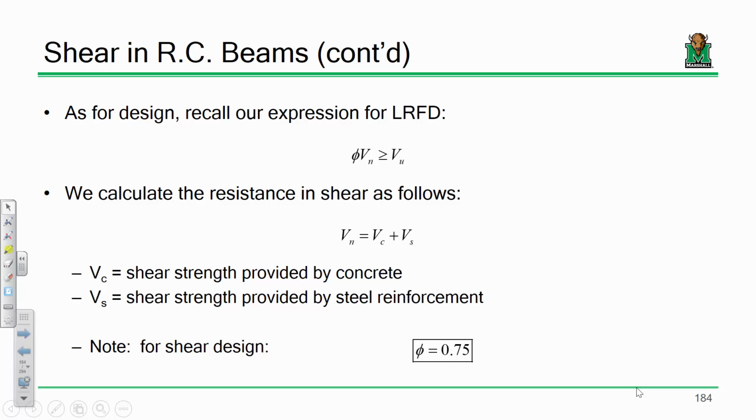We're not having to worry about that here. For shear, because we're dealing with just sum of forces in the y direction, we're not having to deal with strain determinations. Phi is just a constant 0.75. So for this entire aspect of shear, phi is a constant. It's just 0.75. That's it. But it's a lot easier from that perspective. The math is a little bit more doable.